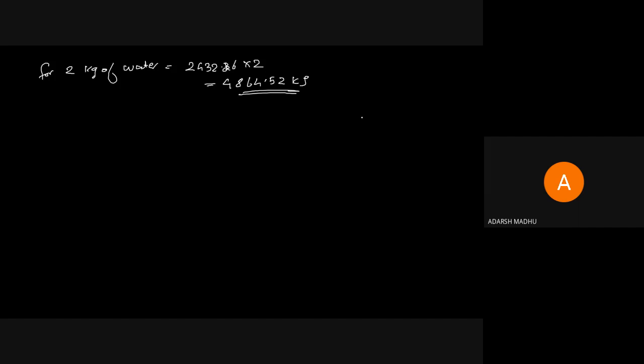Enthalpy of steam by taking the value from the steam table, and that particular value will be a maximum value, and you want to subtract the sensible heat of the water from that particular enthalpy to calculate the amount of heat required to supply it. Sensible heat is mc delta t itself.